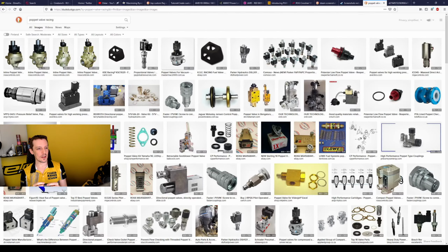But even if you have reasonably large size, so if you have a ball type granular material or something like that, I think you could probably use poppet valves for that type of system also, because those would probably be forced out between the sealing areas.